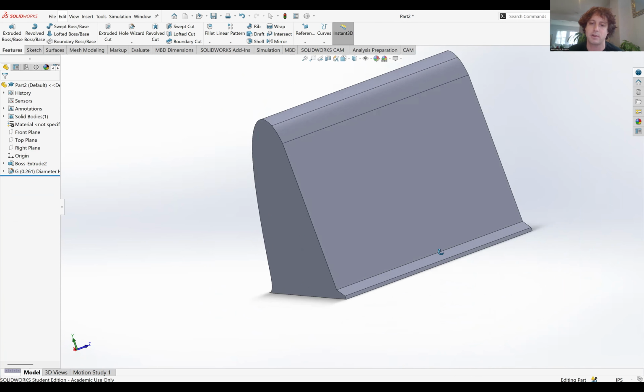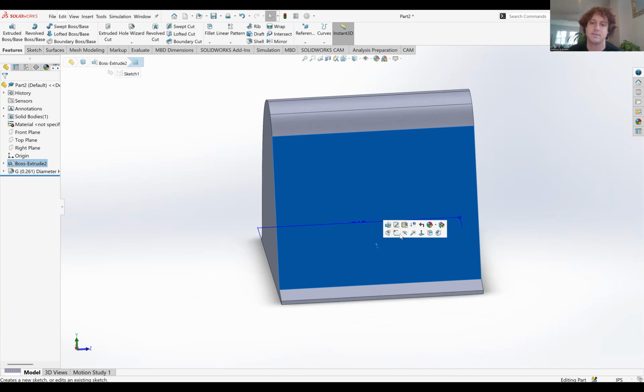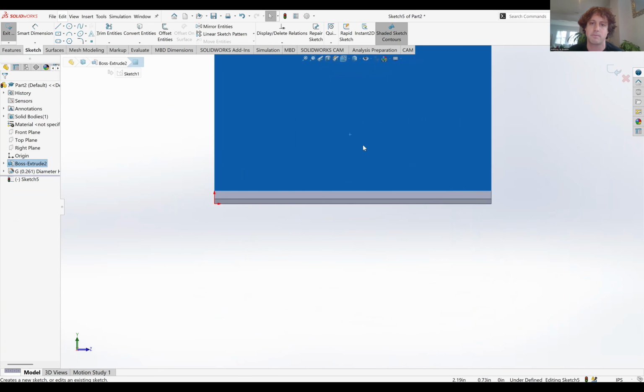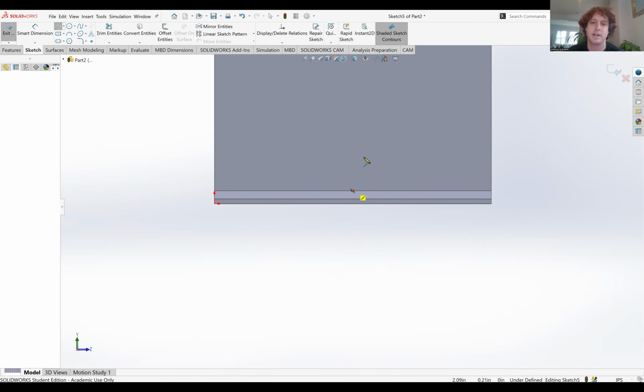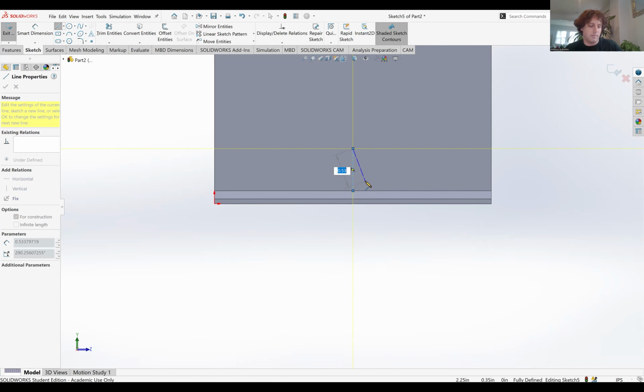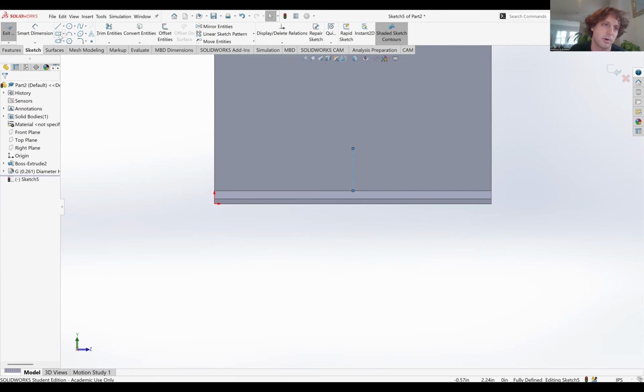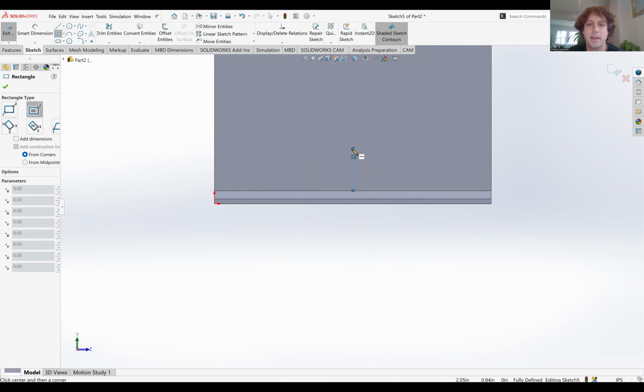Okay. And now we need to make a little portal for the nut. So I'm going to click this face, which is where that portal is going to come from. First I'm going to go to the center line tool, do what I did before and grab the midpoint of that edge, and go vertically up from there. Then we're going to select the center rectangle from the drop down. If you don't have it selected, instead of the corner rectangle, do the center rectangle. And then we're going to do square from there, and drag it down to the edge.